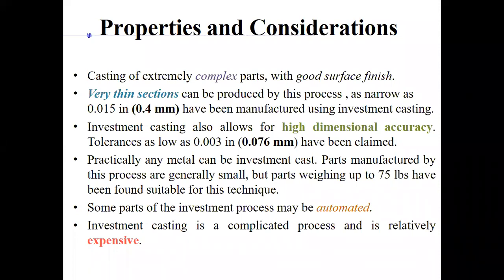That is the most expensive part, we can say, to be able to make that die with all those features that are required, because the features on the inside of the die will be the features required on the casting. So the more complicated the features, the more design detail is required in that die. That makes it expensive.